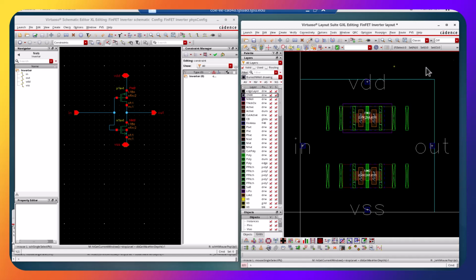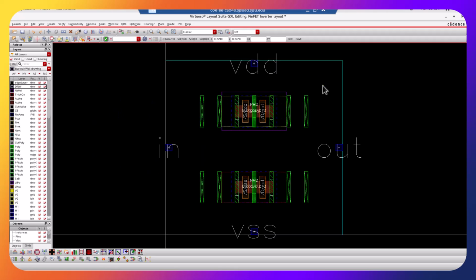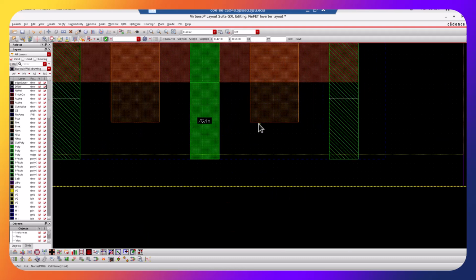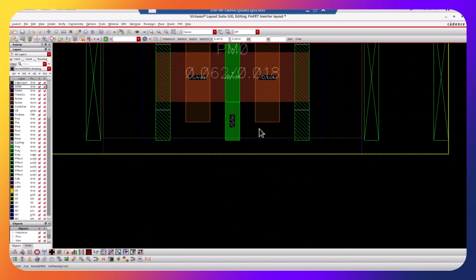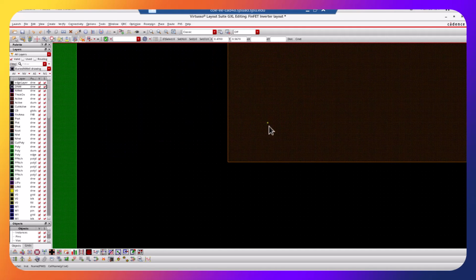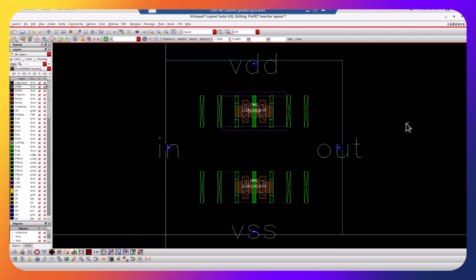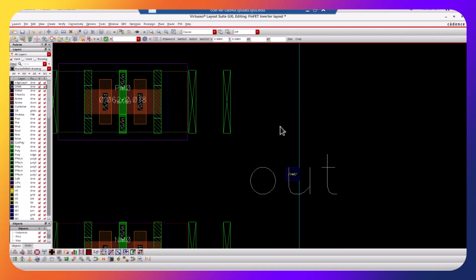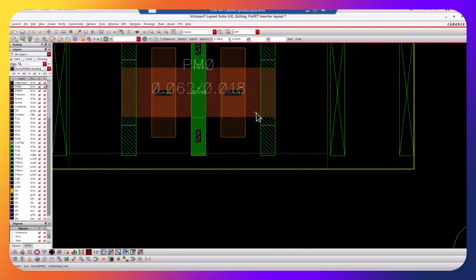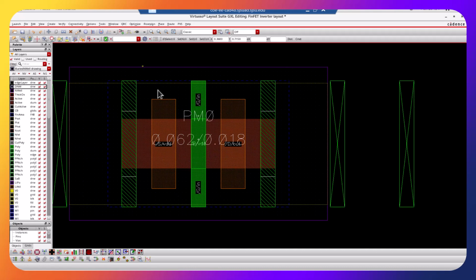Now you see the layout, right? So let me just maximize it. Again, just F, lowercase f. I use the middle button to scroll. I have a mouse, then I can zoom in, zoom out. Use the right button to, not right button actually, I need the arrow key. How to pan using the mouse? I don't know. Just use the arrow key, right? Arrow up, arrow down. Do you see this? Now, if I just try to measure it, type K, right? So let's measure this one, top to bottom. This is 62 nanometer. So let me turn off the light.